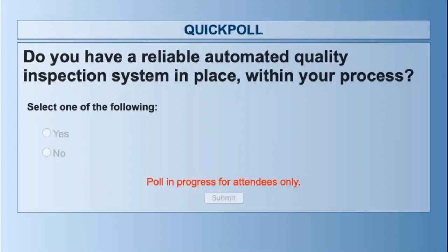But typically, it's not in line right after the dispenser system. It could be down the line of the process, or the robot has to flip around the product in the bathtub case where they're looking at it and doing a visual inspection. But it's very difficult. They can't see heat, so what they're looking for is gloss or reflection from the adhesive. So I've seen a lot of different things like that.